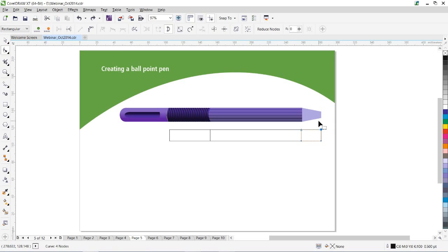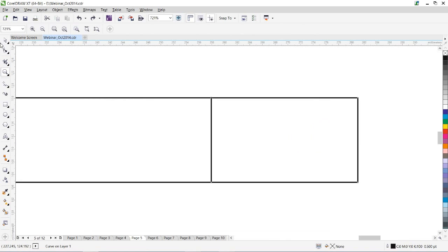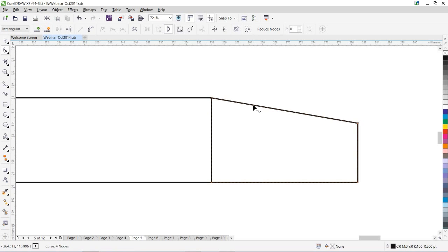Now, modifier keys are Control, Shift or Alt, or the combinations thereof. So if the nudge is set to 2 mm, I can move this node or the object by shift clicking the down arrow key, double the size which I have set.